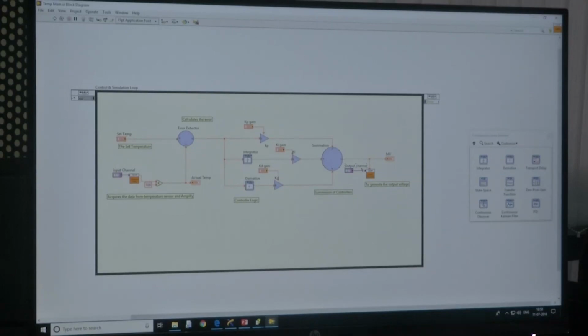But the analog input channels as well as the analog output channels have a particular range above and below which you cannot work. The range of analog input is a maximum of plus or minus 10 volts, and even for analog output it is plus or minus 10 volts. Since it is a simulation, by observing the logic that we have created, the output channel can also provide higher values. So in order not to damage our signal conditioning units, I will be creating a stop execution, and I will show you.